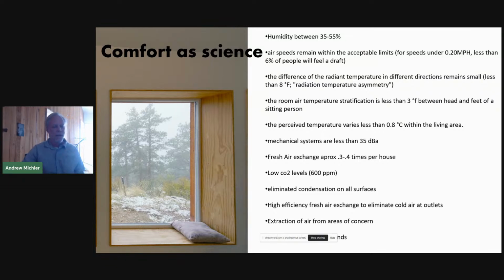And we take the stale air out of bathrooms, kitchens, mechanical rooms, other places where we want to evacuate air rather than having it mix in the house. Same with carbon dioxide. We don't want carbon dioxide, especially in bedrooms, to pick up, and people get sleepy and kind of lethargic once it gets to 1,000 parts per million. Once you get into commercial buildings or schools, it makes a big difference, like in a classroom setting, to have low carbon dioxide levels.